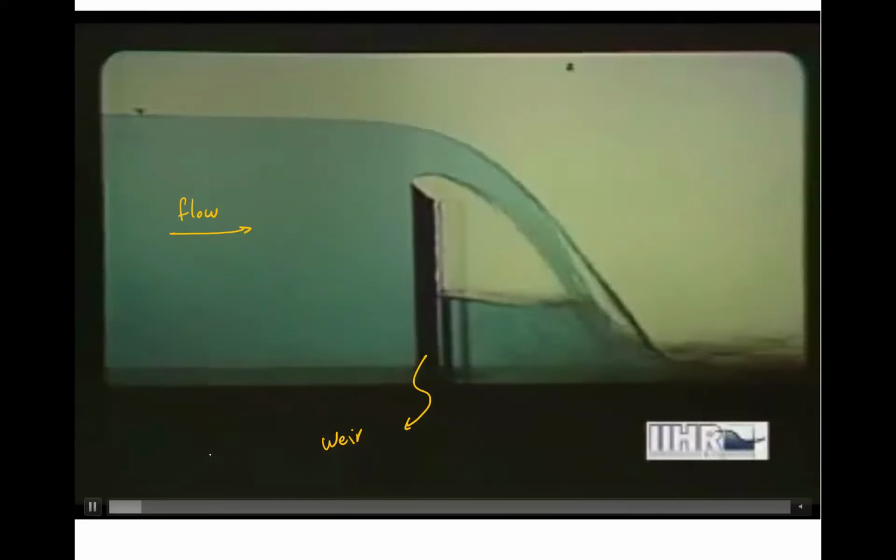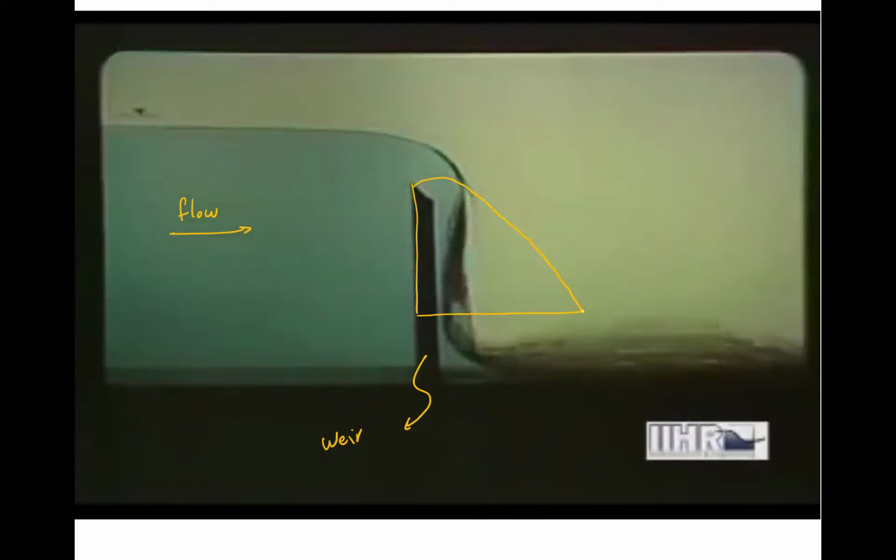But okay, that's typical. Flow goes, becomes supercritical downstream. We don't really see a jump here, at least not yet. And what happens here is that these have this kind of space underneath the jet, which is the OG profile, as we saw before. And what happens over time is that the flow is going relatively fast, and it's dragging air with it.